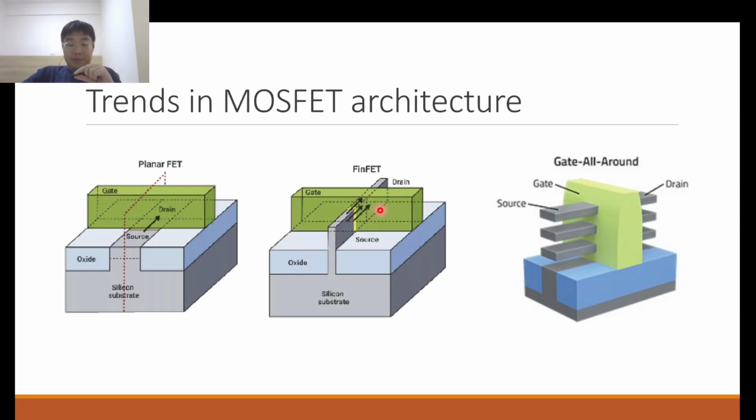So physically, this means that we tend to have lower subthreshold leakage current and better subthreshold swing, because it's easier to turn on the device when we have more surfaces of the gate in contact with the channel. So these are very favorable electrical characteristics of a FinFET device.